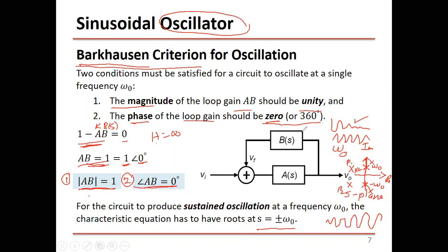So you need to have something that sustains this by keeping omega 0 and minus omega, the two poles, exactly on the imaginary axis. Something else could happen if you design them to move to the right. In this case, they will keep growing, theoretically or ideally, to infinity. But in reality, since these circuits are biased through a certain voltage VCC and minus VEE, or VDD and minus VSS, this oscillation will saturate at these values at the end. So they will be clipped at VCC positive and minus VEE negative. So you cannot have this forever.